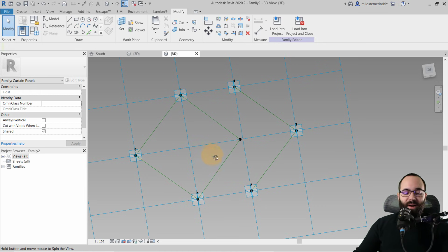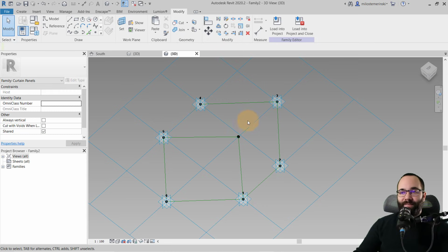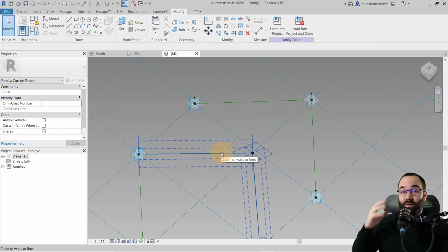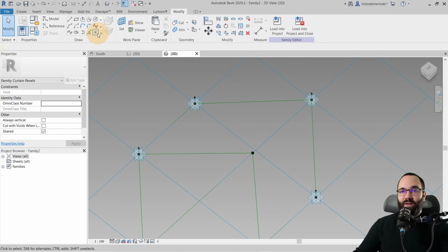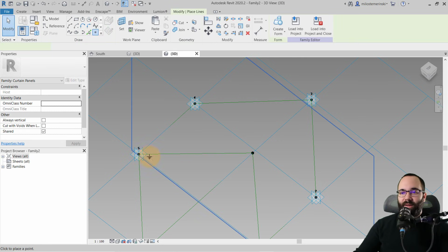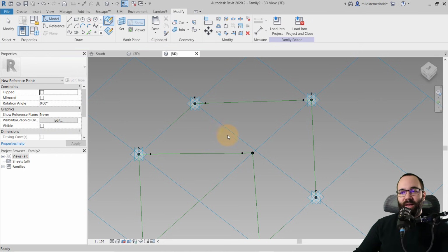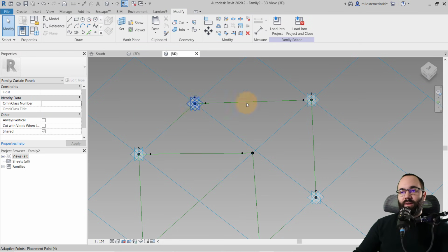So anyways, now how do you create the actual openings? For the openings, we have to create additional framing for a void that's going to be cutting those openings. So you just want to go here to point element, and then you want to place 2 point elements. I'm just going to be showing you in this one corner here. So you just want to place those here, here, here, and here.